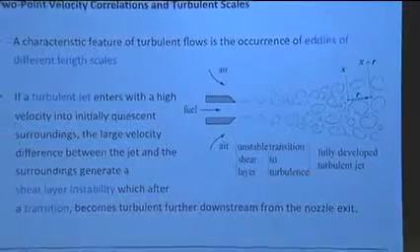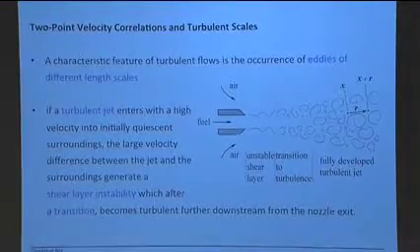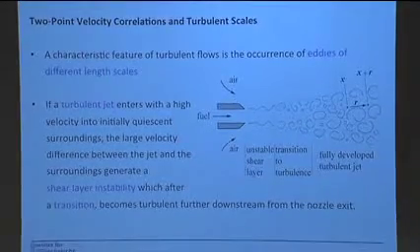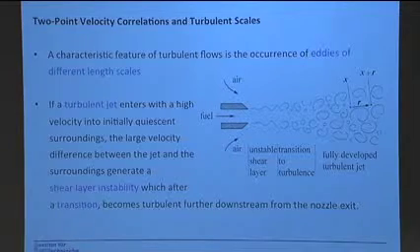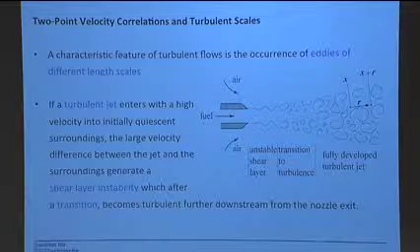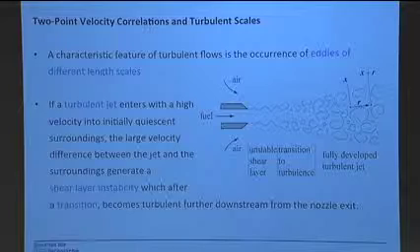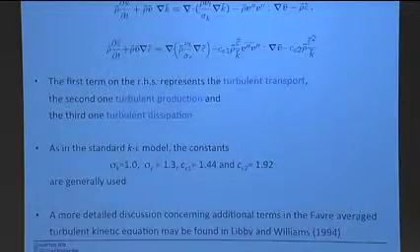And for these large eddies and for the intermediate eddies, the viscosity or the diffusivity is not important at all because the Reynolds number is large. These nonlinear processes are much stronger than viscosity. You go to these smaller eddies, then all of a sudden viscosity becomes important, and you dissipate these eddies away, and so below a certain scale there are no more eddies.